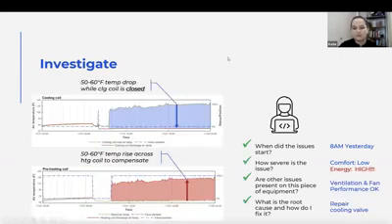But I look further, and when I look at my preheating coil and my cooling coil, I see something strange. I see that my discharge air temp set point is 55 degrees and my cooling coil is closed. This little dashed line here shows me my valve position. So I should not have any chilled water going through that cooling coil. I should not see any temperature difference across that coil, yet I see a 50 to 60 degree temperature drop. That would send off some alarm bells to me that there's something wrong.